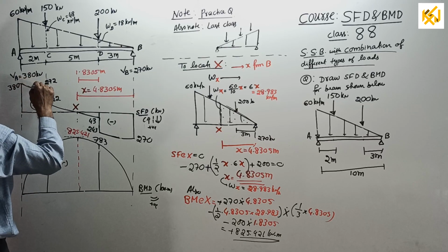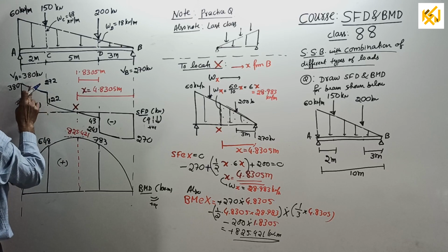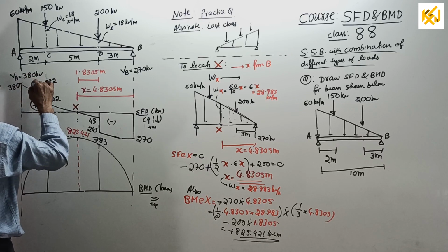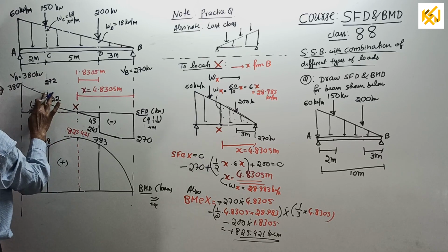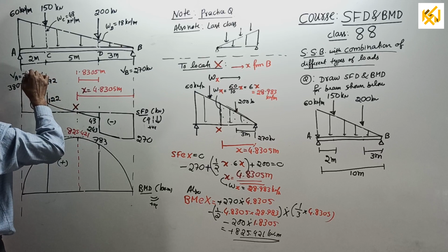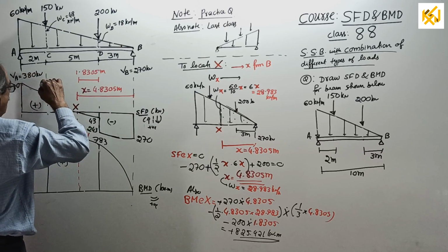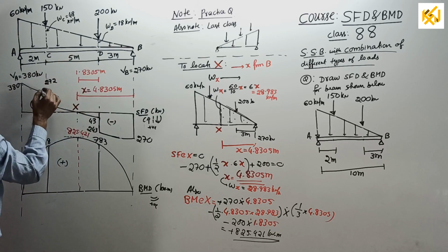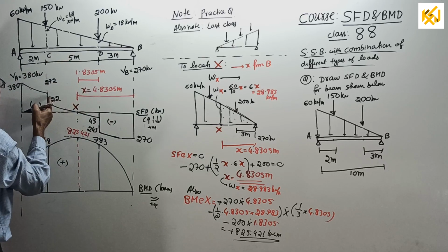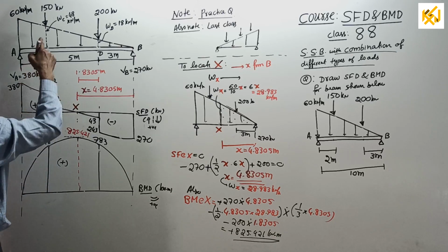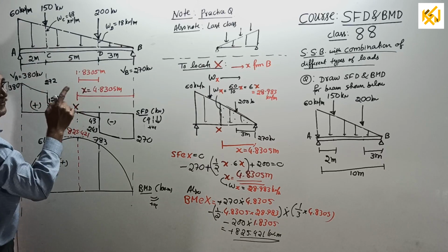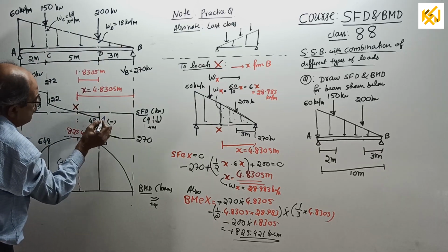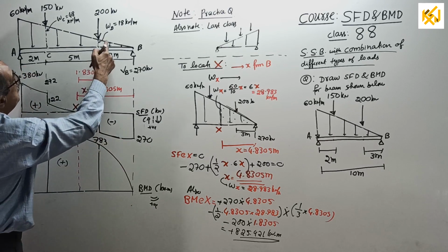Okay. If I make too much correction, then everything will go. Once again, I have to write now. See, this way, the slope a little more actually, because the same slope should be there at both ends. That's why I don't want corrections at all. Now this way the slope, here also this way. And one more thing, see here. If I draw a tangent here and a tangent here, the slope should be how much? 48. Why? The slope of the SFD is the intensity of load. Here also, if you draw a tangent at the end portion and starting point here, the slope should be 18.